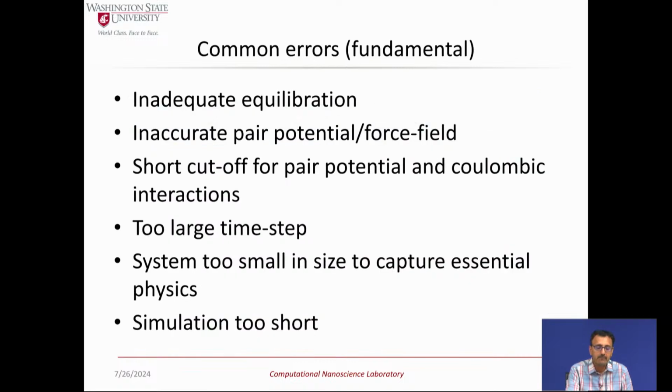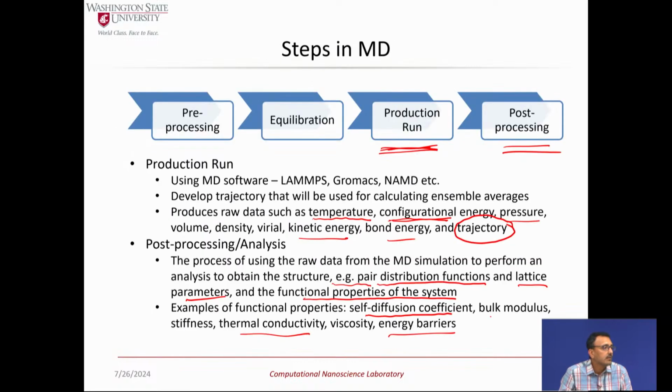Okay. So, sir, in thermal conductivity, we usually have contribution from the electrons and the lattice. Mm-hmm. It's vibrational thermal conductivity. So, is it the vibrational one or everyone? The MD simulations capture the phononic vibrations. It is not able to get into the electronic contribution in a straightforward manner.